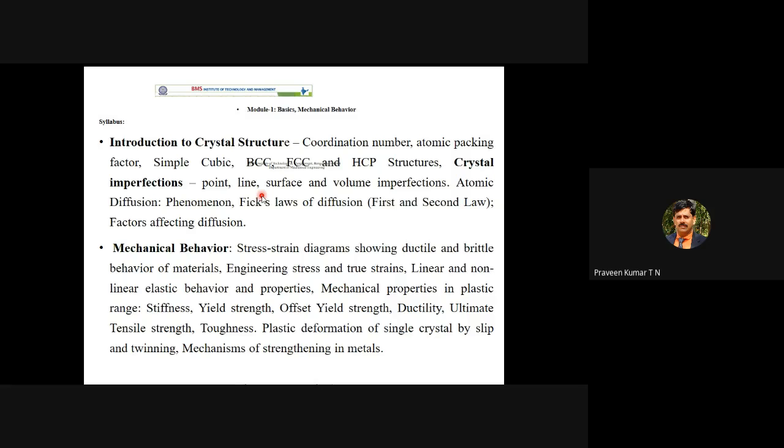In the second part, you already discussed the mechanical behavior of the material. Stress is load divided by area. This is the formula. Or you can say that it is a resistance offered by the material to external loading. There is also strain, and there is a formula for strain that we have discussed: change in length divided by the original length, or deformation divided by original length. Then you have to study the stress strain diagram for ductile material.